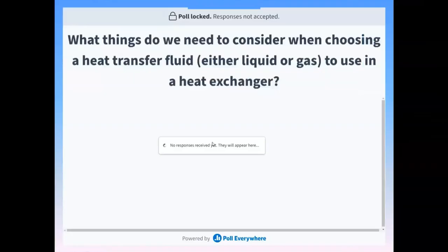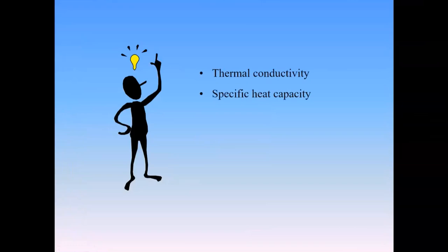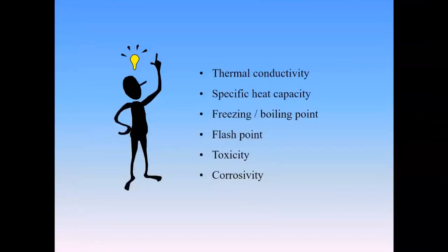And if we think about why or what we might consider to be important in a heat exchange fluid, we have some things like how much heat can it either absorb or give off. So the thermal conductivity, the specific heat capacity. We may think about, is this thing at risk of either boiling or freezing, or do we want it to boil or freeze? So we may want to know what temperatures do those occur at. Is it toxic? Is it corrosive? What sort of cost does that fluid have? And all those things may come into play when we're thinking what would make a good heat exchange fluid.